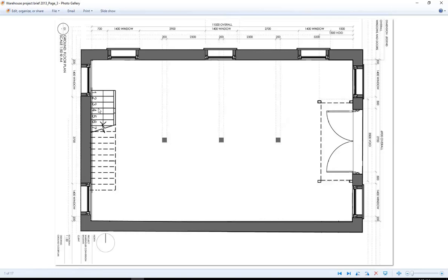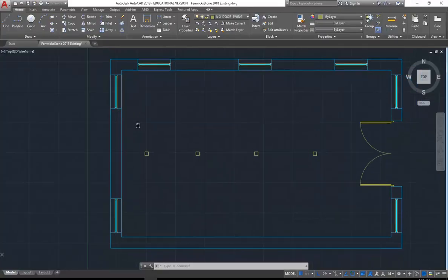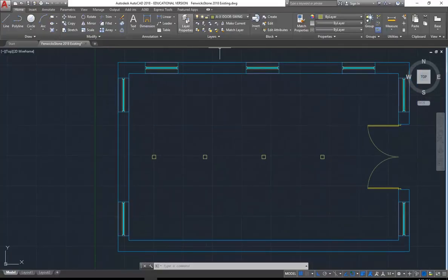And that's typical. Often stairs are not dimensioned in the way that maybe the walls and the other openings are. It's because stairs often have standard measurements for things like the tread, and we can just assume those. So here I'm going to assume they're 250, even though a private stair can be 240. It's an older stair, so they're often not very deep, the treads. And so, again, I can probably safely assume 250. Often these days, they'll be bigger than that. So the minimum, again, is 250, but it's often a good idea if you can go higher than that.